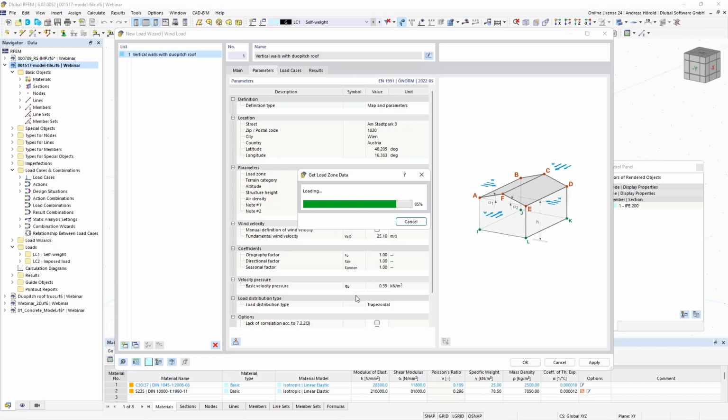For buildings with an aspect ratio of height to width larger than 5, the resulting force is multiplied by 1. And for buildings with a ratio of height to width smaller than 1, the resulting force may be multiplied by 0.85. And intermediate values are linearly interpolated.